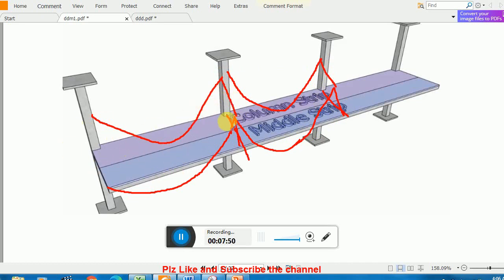Now to cover these movements, you have to provide longitudinal reinforcement in this direction. For this positive movement, you have to place bars in this direction, and similarly for this negative movement, you have to place bars in the upper portion of the slab. So this is how you can understand the mechanism.